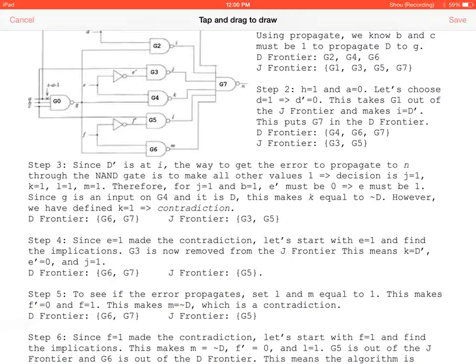So the next step is we want to take this guess again. Recall earlier we set all 4 equal to 1 because we want to propagate it through on the NAND gate. So what we're actually going to say is, let's see what happens if we just make the last two 1, right? That would make life simple. Well, is that going to work? Well, we have 1 on the input for G5, right? So we don't have a 1 here for an AND gate. That means F bar has to be 0, which means F has to be 1.